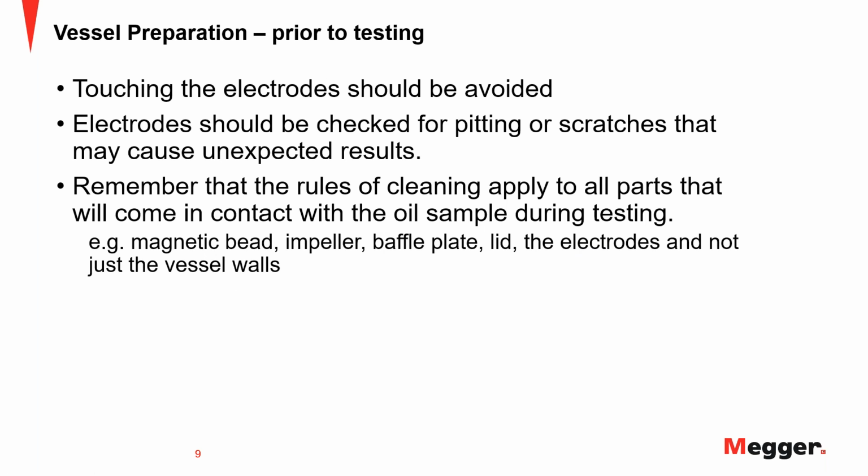And remember, cleaning doesn't apply to just the vessel walls itself. It applies to all of the parts that come into contact with the sample. So this is the impeller, the baffle plate, the lid, the electrodes. Everything needs to be cleaned and also flushed with the sample oil before you proceed with the test of that sample.